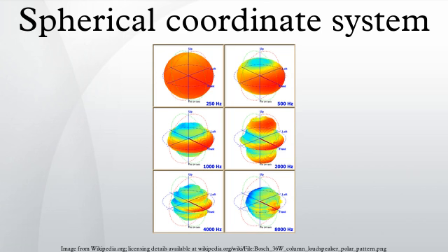To a first approximation, the geographic coordinate system uses elevation angle in degrees north of the equator plane, in the range −90° to 90°, instead of inclination. Latitude is either geocentric latitude, measured at the Earth's center and designated variously by ψ, q, φ′, φc, φg, or geodetic latitude, measured by the observer's local vertical, and commonly designated φ.